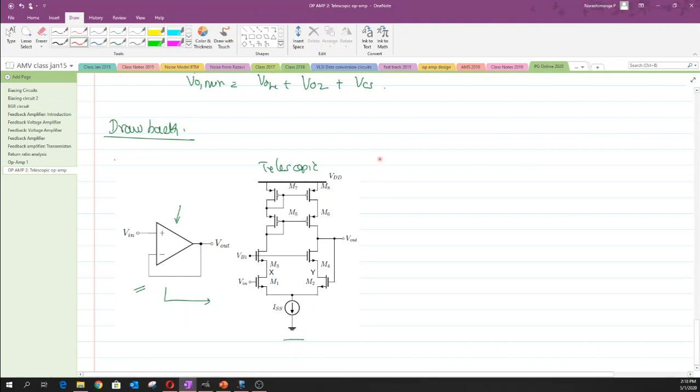So now with respect to M2, we want this M2 to stay in the saturation regime, and let us try to put down these expressions, like how the value of VGS with respect to VDS has to be related such that the transistor M2 is staying in the saturation regime. So we know that the drain potential of this M2 can be written as Vy, right.